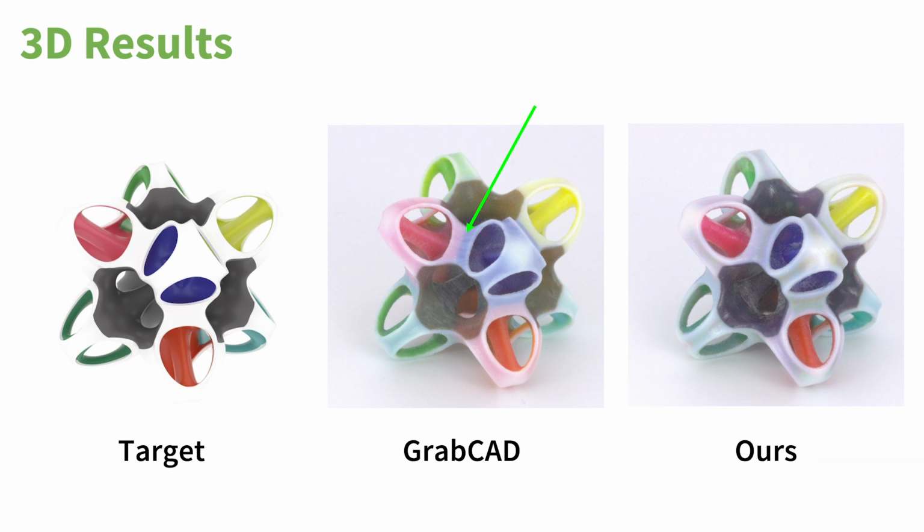And this is what comes out of the default 3D printing driver, and you see that the input should actually be red from one side and white from the other side. Of course, if you send it in, all of this red color will bleed through, and you will not be seeing the white as you should. Again, if you send it to our algorithm, you get a much more faithful reproduction of the input, of course within the limits of what is physically possible using this technology.